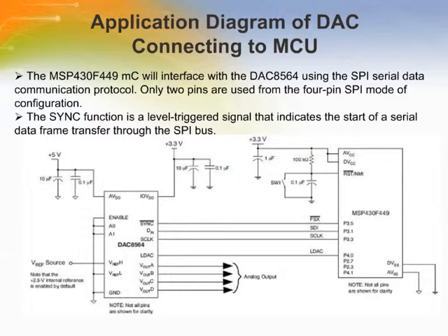having the MSP430 microcontroller be enslaved by another host peripheral for SPI purposes. Therefore, the STE and the MISO functions in SPI mode of the USART0 port are not used. The DAC 8564 receives a 24-bit digital input word serially because the SPI only provides 8 data clocks per transmission. 3 write cycles are required within the sync low period to complete 1 write cycle to the DAC 8564.